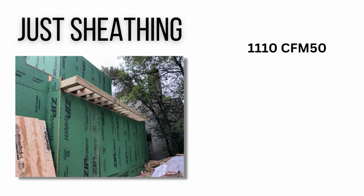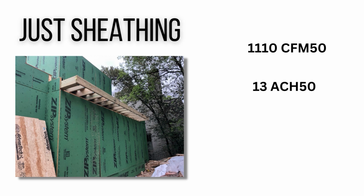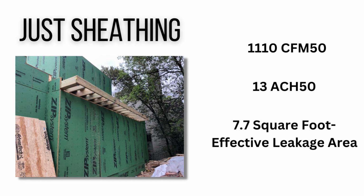Now, you typically don't test sheathing, however, we did, because we wanted to see what it would look like if we did not put any tape or any sealant. And it was still pretty leaky. It was an improvement over the original house, which didn't have any sheathing. It just had plaster and some drywall as part of the renovations. So we got it down to 13 ACH 50, which is about a 7.5 or 7.7 square foot hole, which is still smaller than the other one, which was 12 feet, but it's still pretty leaky.